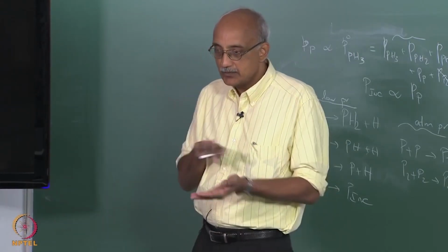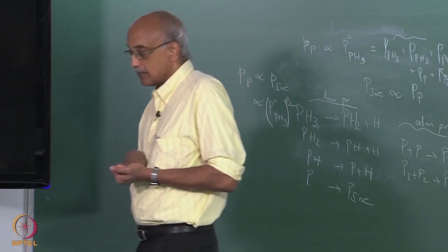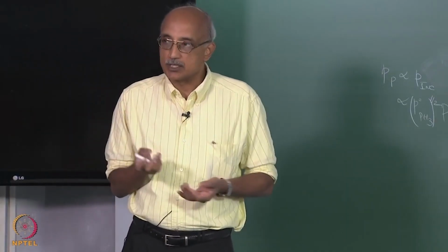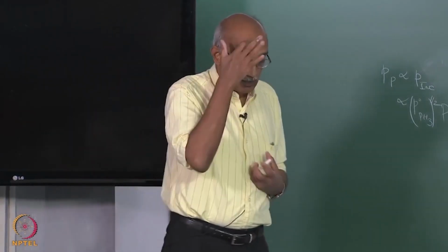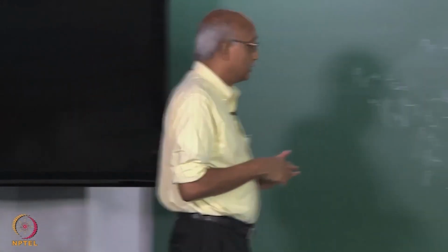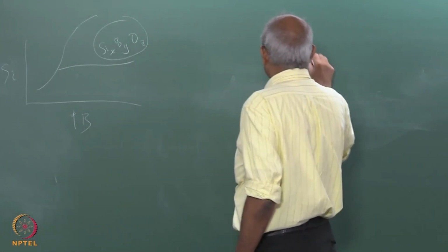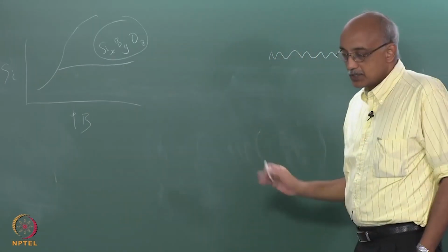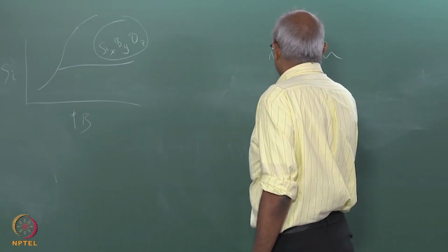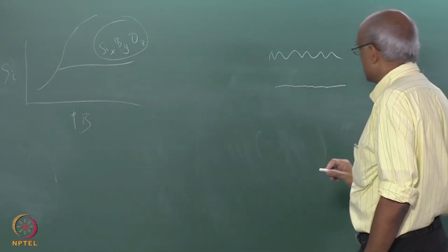In other words, as the CVD film becomes smoother and smoother, its capture efficiency or sticking coefficient for arriving molecules will change, and the change is not always positive or negative. For example, if you have a glass surface that looks like this, and let us say that by putting in some additives and flowing it at high temperature, you have been able to make it look much smoother on a microscopic scale.